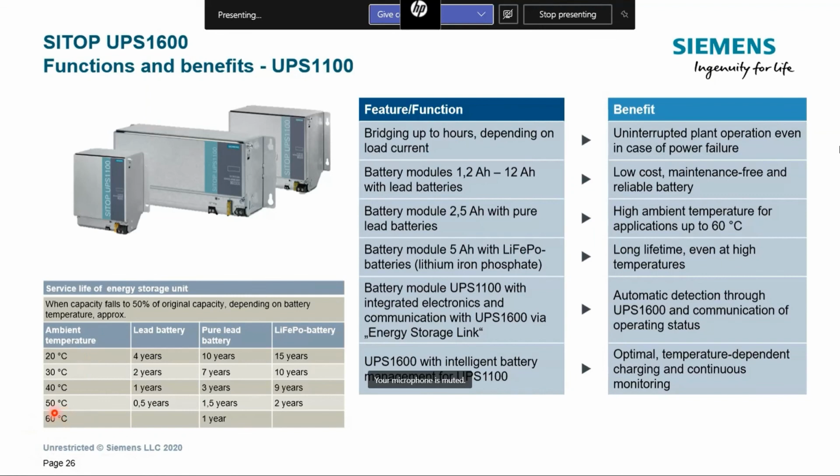So even if you are in an outdoor panel installation and the temperature might get to 50 degrees, then yeah, the battery will not live half a year, not really, because you have winter and summer, and you have day and you have night. So the average temperature is actually what we are looking for here, which is usually, for example, 40, then maybe it will live for a year.